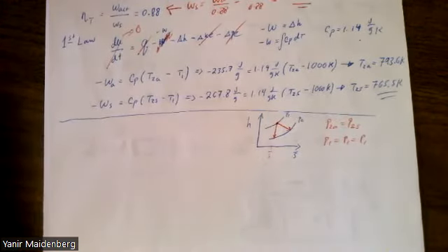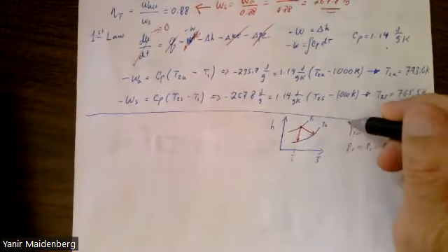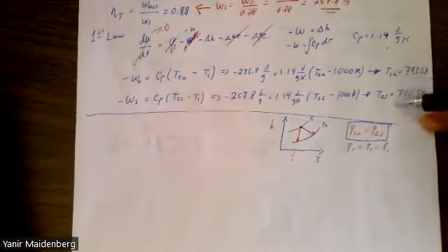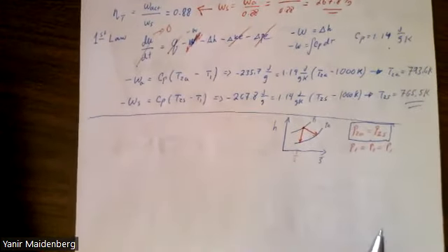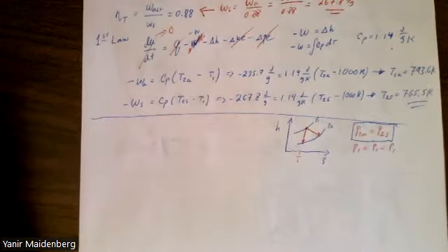So what we need to do is just evaluate the isentropic pressure, and that will give us the outgoing pressure. It's important to understand that you don't have to evaluate two separate pressures here. You do have to evaluate two separate temperatures, because pressure is not a metric for irreversibility for a turbine; the temperature is what's really dictating whether something is isentropic or not.